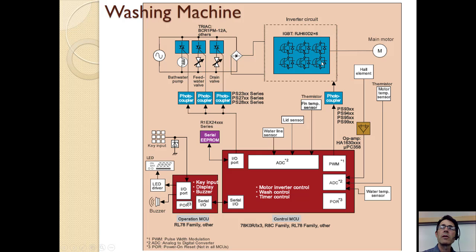Now what you see here, if you've taken a course and learned a little bit about transistors, is kind of like an H-bridge, except it's an H-bridge for a three-phase motor. So each of these transistors can drive current one way or the other through one of the three coils of the motor. And in doing it in a certain sequence, you can change the direction and the speed of the motor. So that would be your electronics, the mechatronics over here.